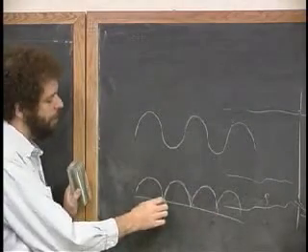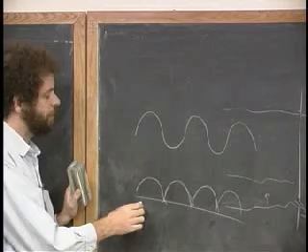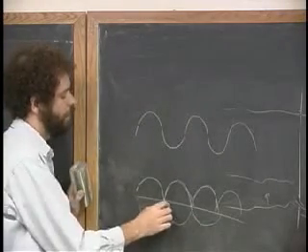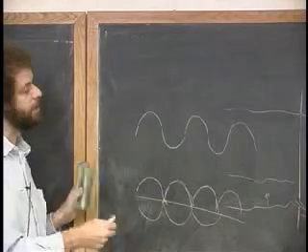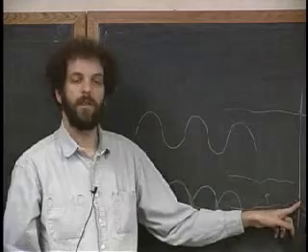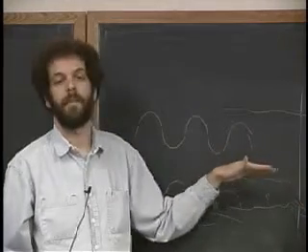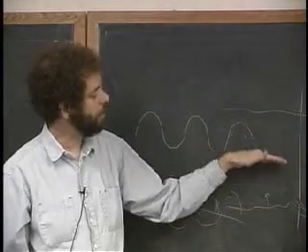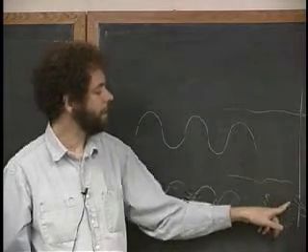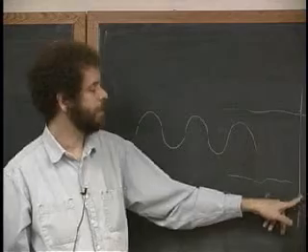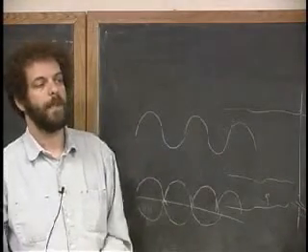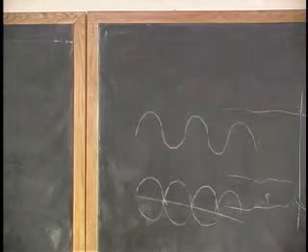And the transistors are all switched when the voltage between the positive rail and the negative rail is 0, like right here. And that's the same as saying that I'm not going to change the door from open to closed until the levels are the same. And I'm going to raise and lower the levels here slowly enough so that I will dissipate no net or as little net energy across the door as I possibly can. And this actually works. Okay?